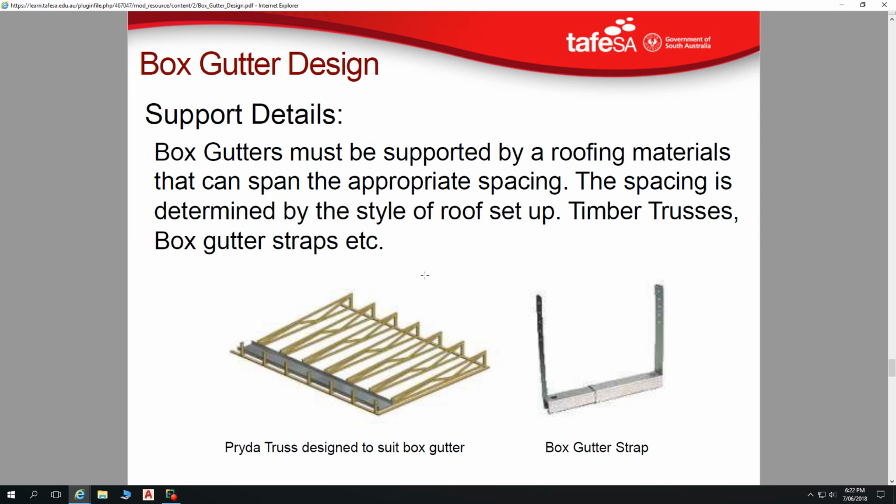So box gutters must be supported by roofing materials that can span the appropriate spacing. Spacing is determined by the style of roof setup. So that's for timber trusses, so a typically residential scenario. This box gutter strap is more what's used in a commercial setting.